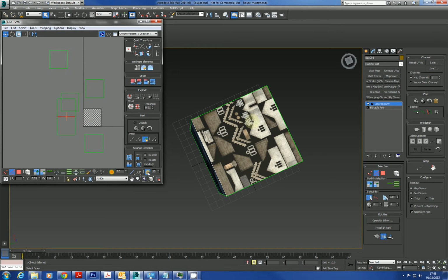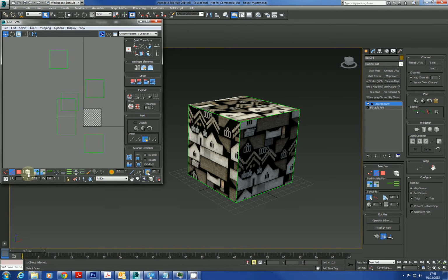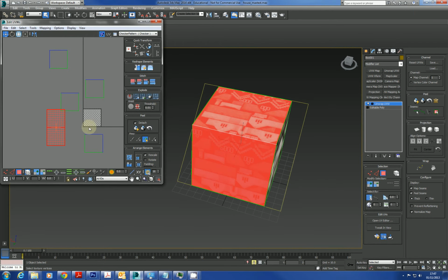It's pretty much doing the same thing still, but it's utilizing the full texture. If I click onto the faces, these faces are now stitched together. They're functioning as one joint face. So if I click on this, it allows me to select not just one face, but all the faces that are stitched as one component. If I let that go, I'll be selecting only each individual face. But if I have this, all the faces that are stitched to this one section will be selected. In this case, it's these two faces here.